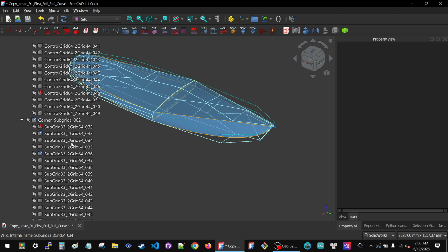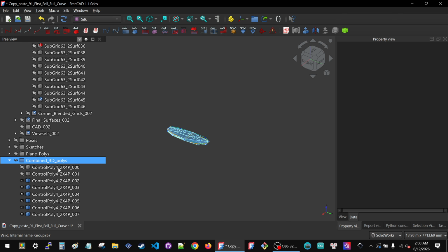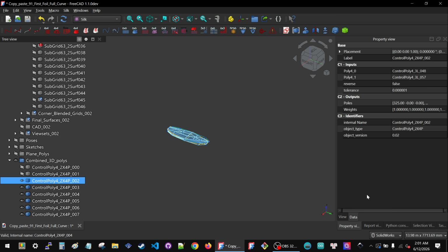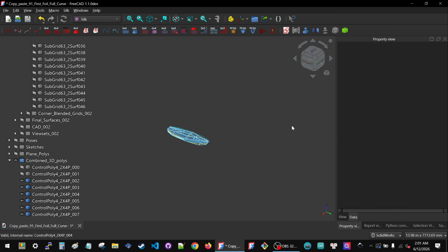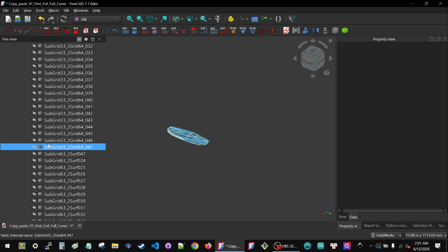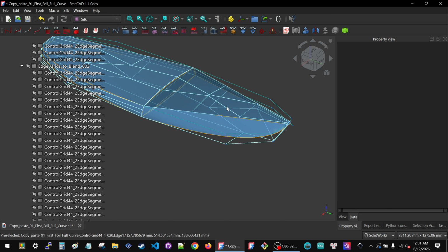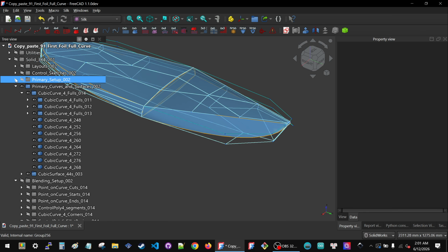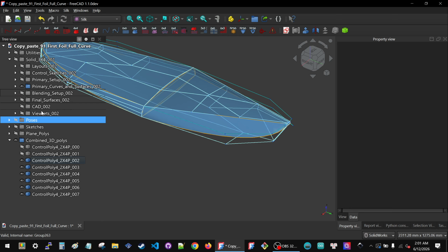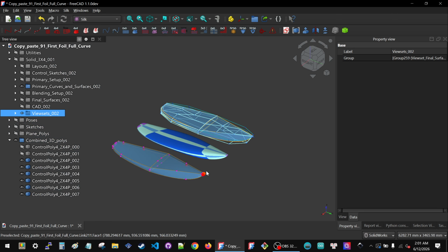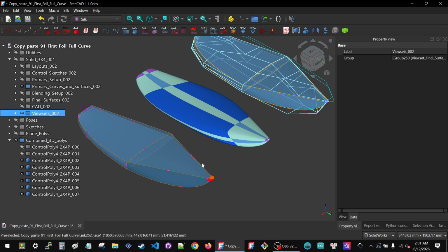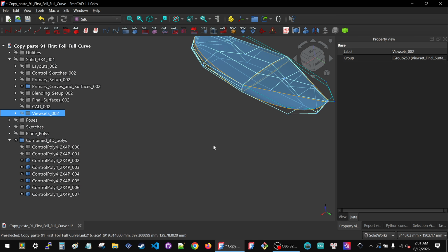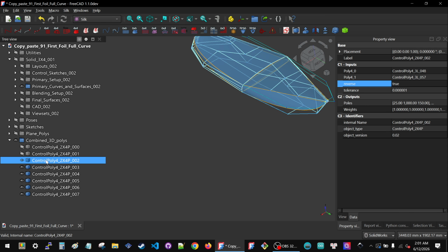But it's giving me errors. And again, if it's giving me errors, that means that I should have the polygon reversed. Set that to true. All the errors are gone. Let's go ahead and do the upper one. No, we're going to do them in order. Close this. Might as well do a QC test. Turn on the view sets. Yeah, sure enough, this curve has updated, and now everything, including the blends, works. So this curve is done. This polygon is done. I hide it.